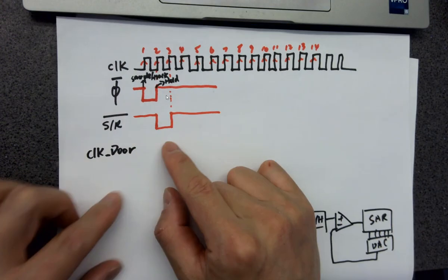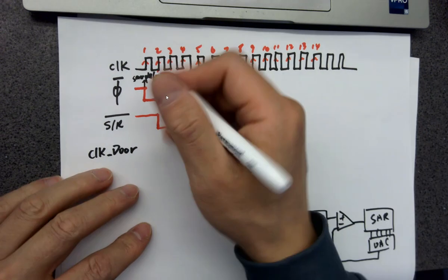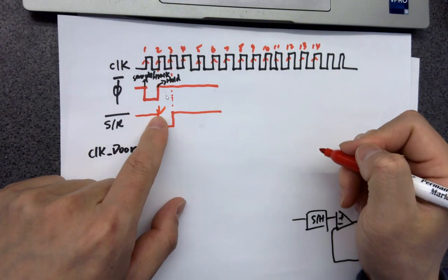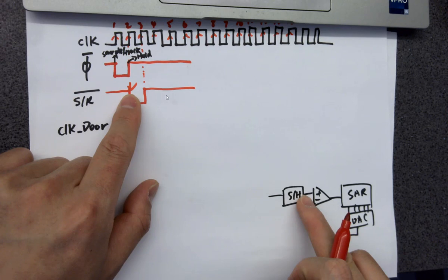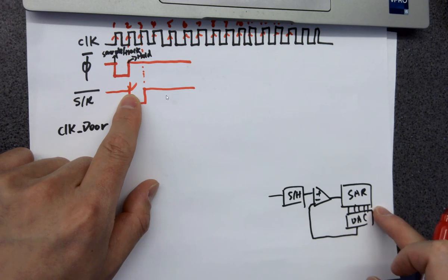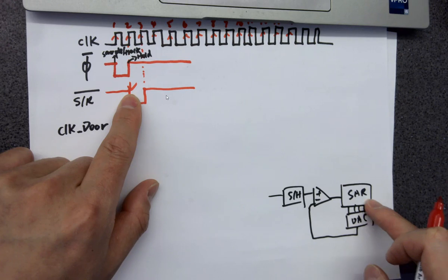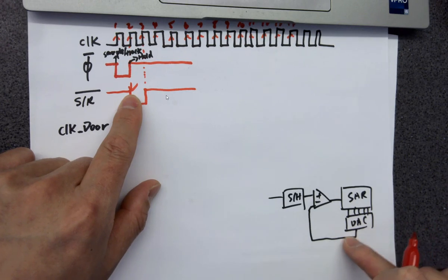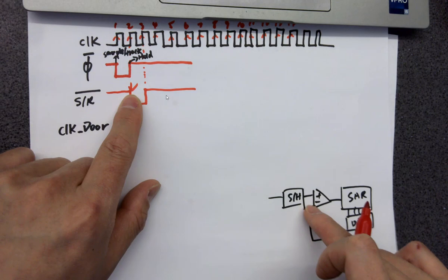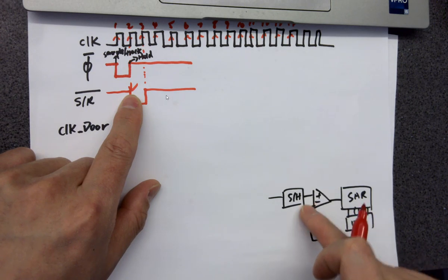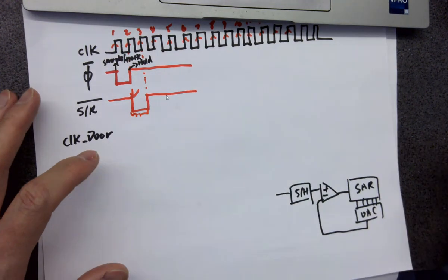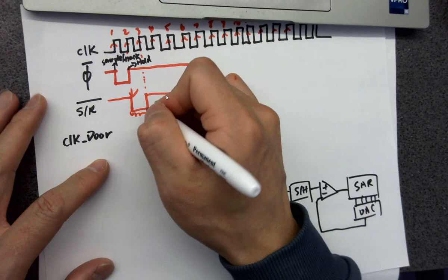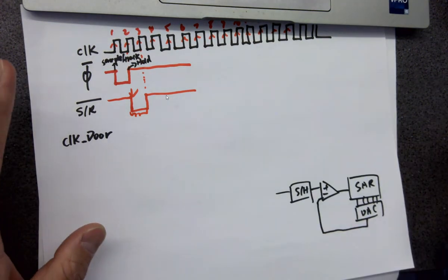Once this one has the falling edge, it forms that 100 state, right? So that 100s digital data will be converted to analog voltage by the DAC, and it will be directly fed back to the inverting terminal of the comparator, and it's already started conversion. So during this period, it's trying to generate A7 if it's the 8-bit ADC.